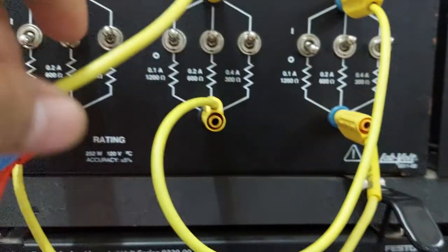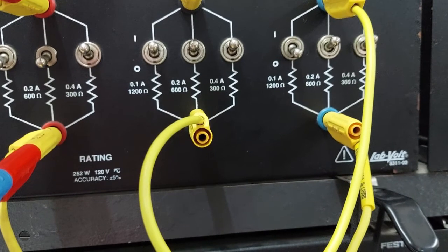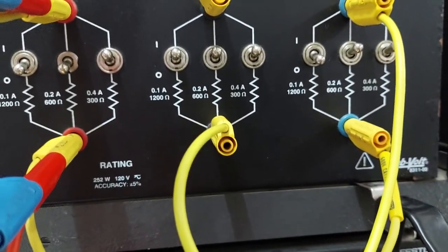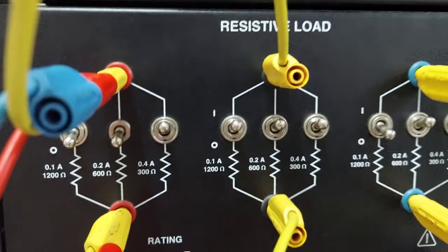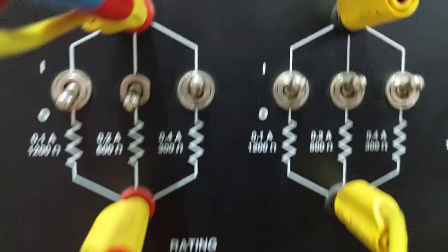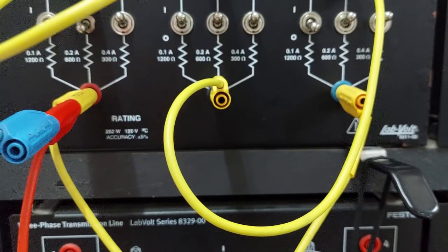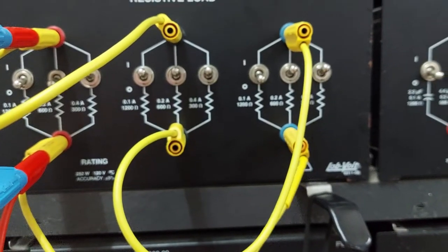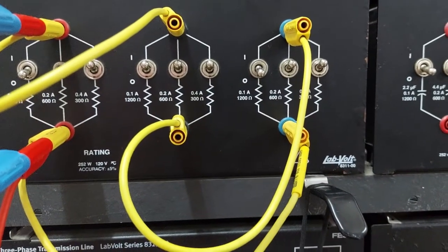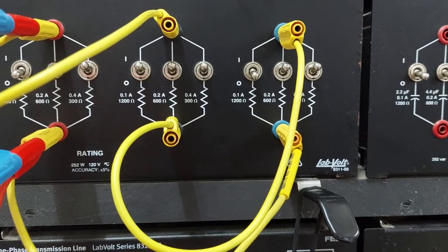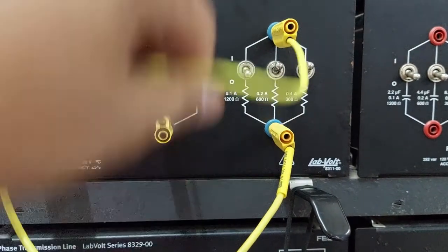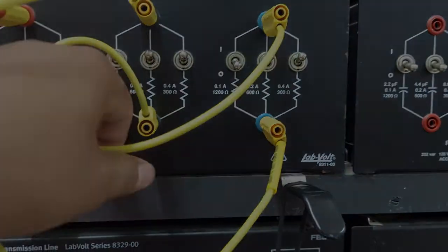Since the circuit is a parallel combination of your R1 to the series combination of R2 and R3, we may say that the voltage of R1 is similar to the voltage of R2 plus R3. So therefore we may connect your voltmeter to the terminals of your R1, knowing that the positive terminal of your E1 is connected to the positive terminal of your R1 and the negative terminal of your E1 is connected to the second terminal of your R1. And of course, your ammeter is connected in series with the circuit.